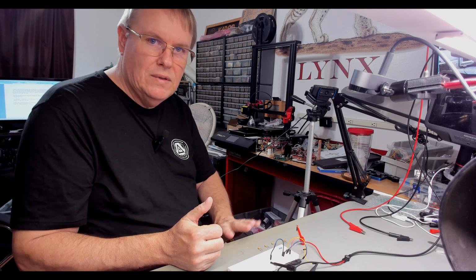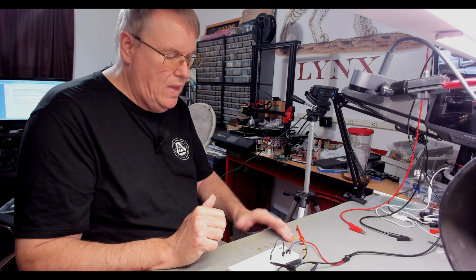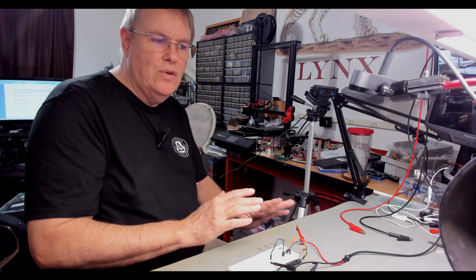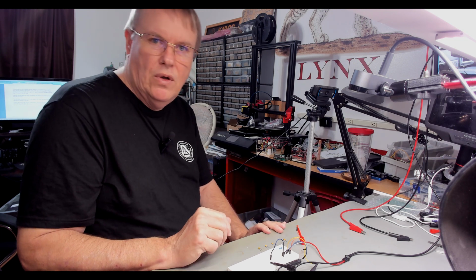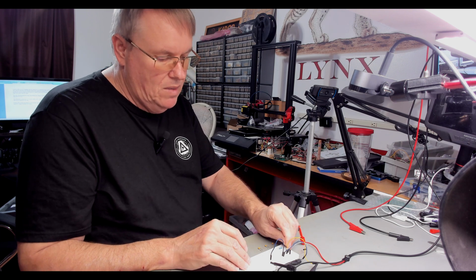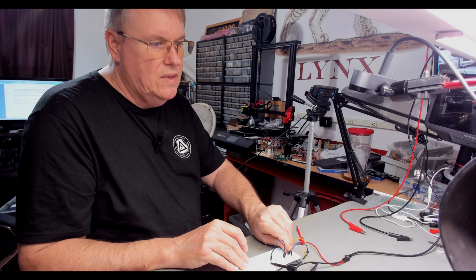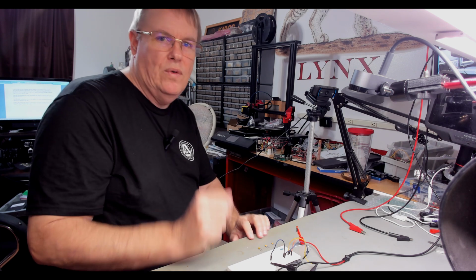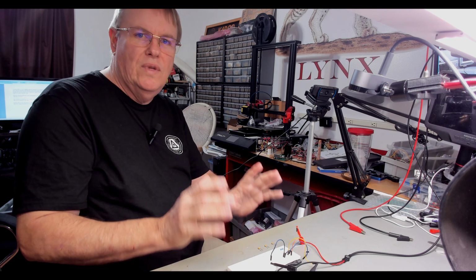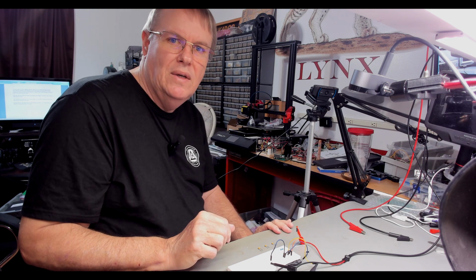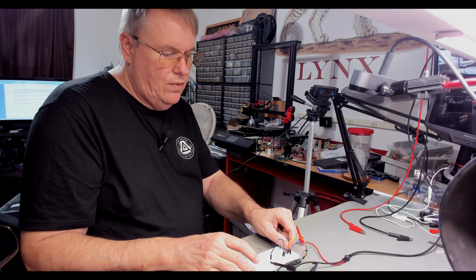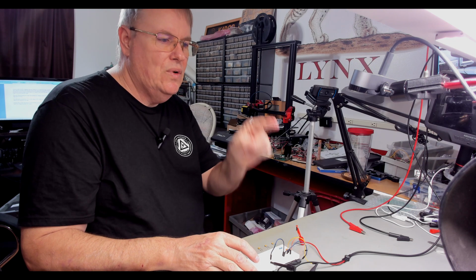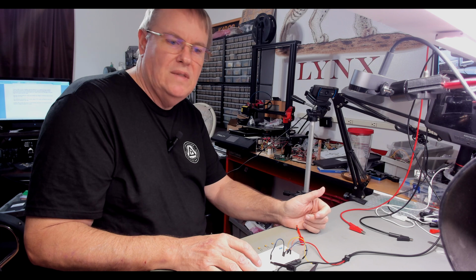There's always losses, but if you go with a large enough capacitor value, your losses are going to drop dramatically and be almost unnoticeable, as with this 10 microfarad. Now, we know that 10 microfarad will block DC. I proved that earlier. We tested that and showed that DC will not pass through a 10 microfarad. So you're still going to block your DC current through this capacitor, but you're going to let pretty well all of your AC signal through.